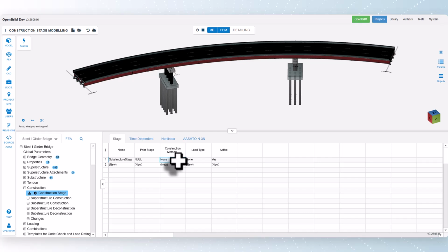For a typical steel I girder bridge, pier construction, steel I girder construction, load application on deck, and transient load stages will typically be defined with the none parameter. However, the stage that represents the deck construction, the deck hardened stage, should be defined with the equal parameter. The match cast technique is typically not used in the construction of steel I girder bridges and is generally applicable to segmental bridges. Now we click the three-dot icon button in the load type parameter and select it.